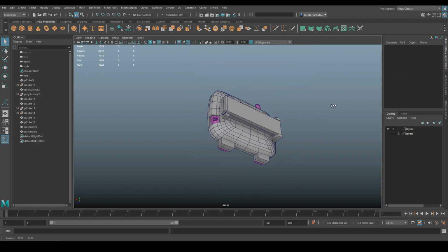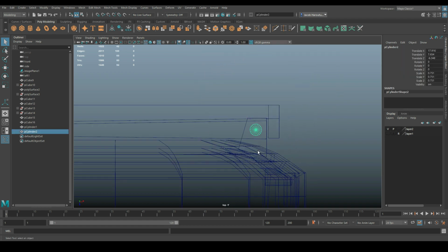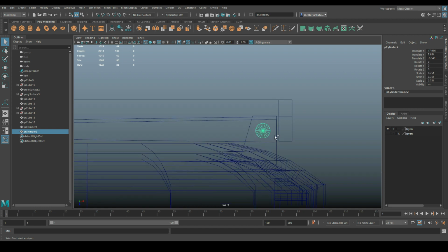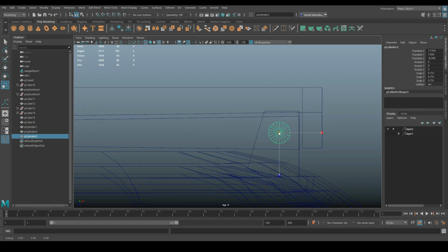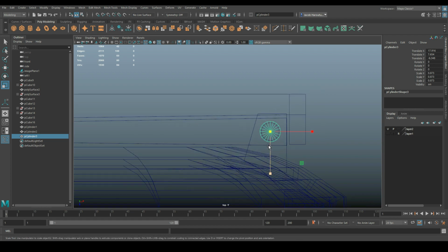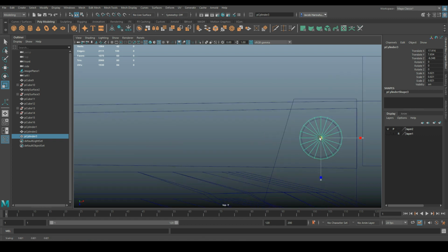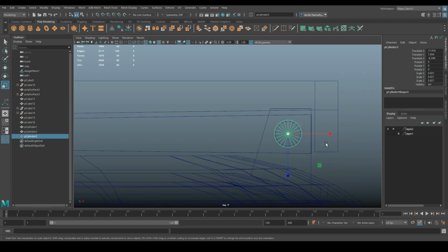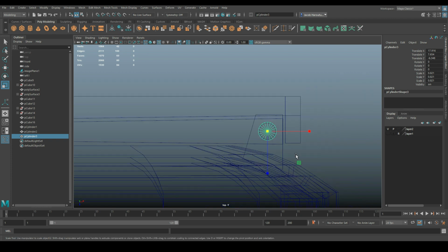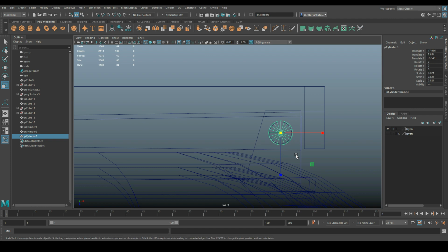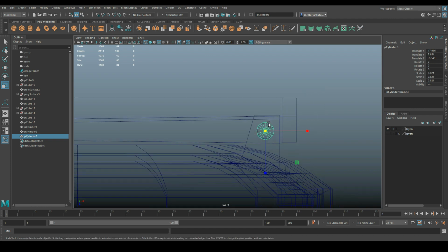So now that we have everything we need here, because I know I want these cylinders to be about this big, I'm gonna have to duplicate it and give it some tolerance so when I create the hole for these, it can fit in. And depending on how tight I want it to be, I think I'm gonna make it kind of tight here, because I could always sand down that cylinder on the inside to make it thinner and fit in there. But if it's too loose, then they'll just be flapping open and closed all the time. And I want there to be some friction there.